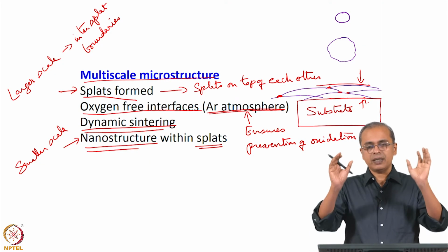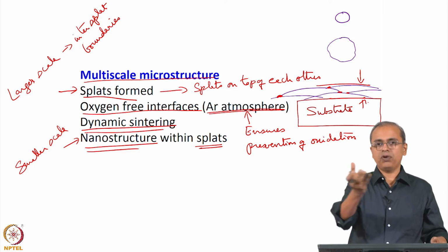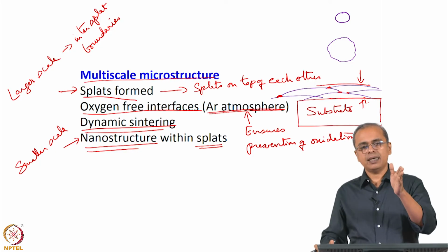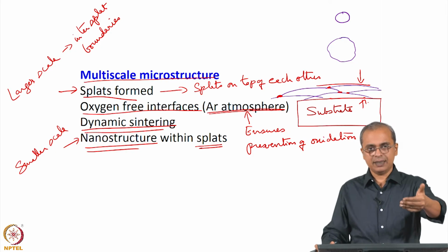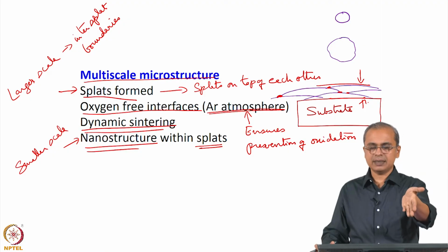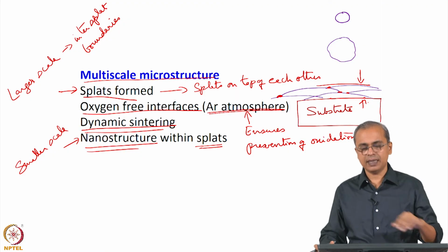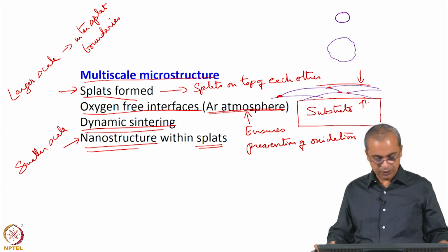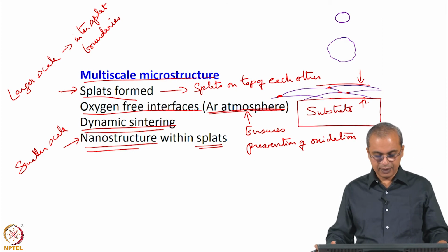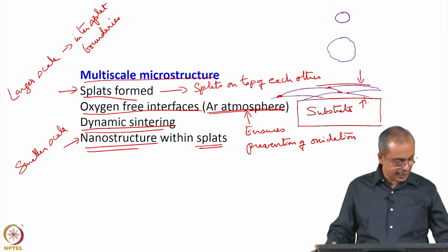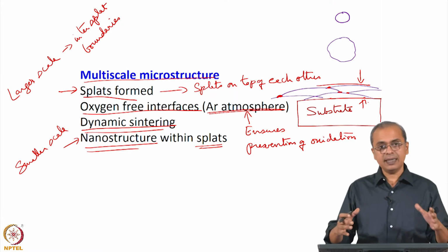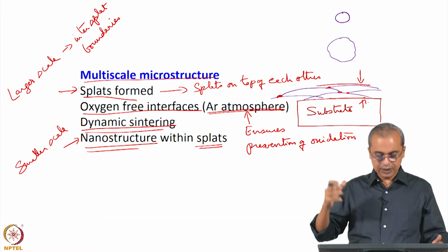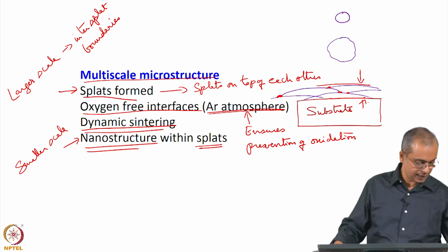So, the sample is like a thick layer which you can form on top of this substrate, and to the extent that you can maintain the thermal gradient, in other words to the extent that you can keep cooling this sample and you can keep heating it with this plasma, you can make thicker and thicker layers. So, like I said, you can make several millimeter thick layers, and once you have done that, you can carefully machine and remove that layer, and you can do various things with that layer.